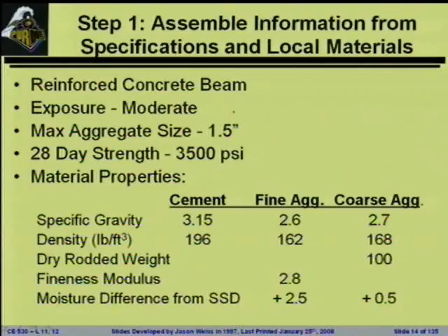So for our first step, and in this class, most of this is going to be given to you. In practice, this is information that you're going to have to hunt around for. We will be looking at a reinforced concrete beam. It will have moderate exposure, and I will give you moderate exposure, although typically your specification is not going to say moderate exposure. You're going to have to determine for yourself what the exposure conditions are.